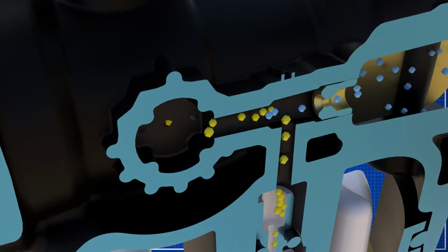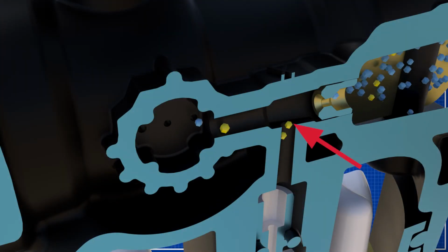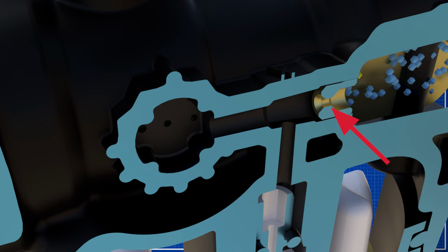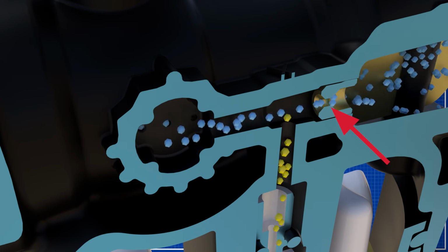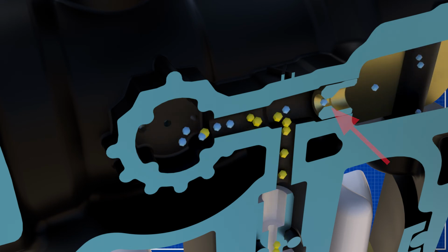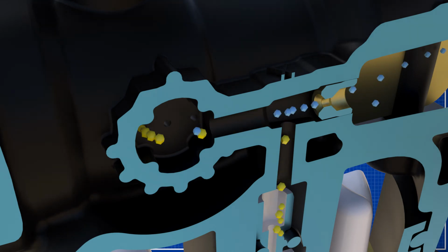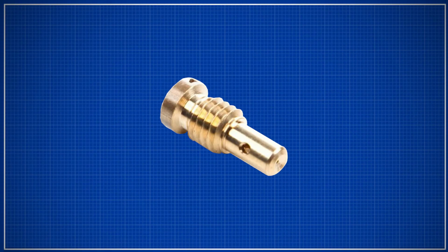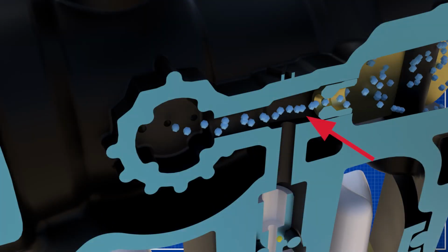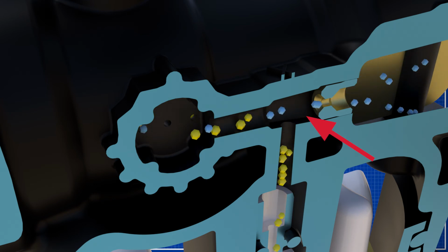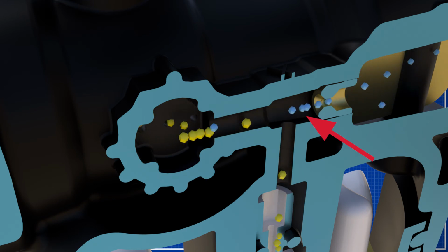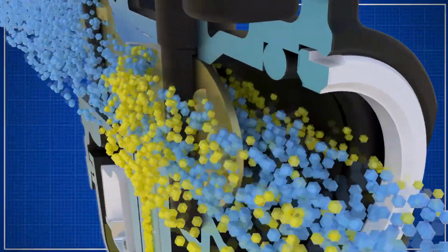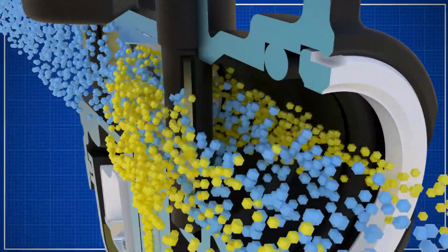The fuel then intersects with the idle air bleed circuit. Immediately before this intersection, the air that went into the air bleed was also metered. Atomization starts at this intersection. Sometimes a pilot jet is at this location. The pilot jet includes the second idle fuel jet. Also, metered air goes into the air bleed passageway. As the mixture moves, it atomizes. The mixture will move to the chamber area to supply fuel for low-speed engine operation.